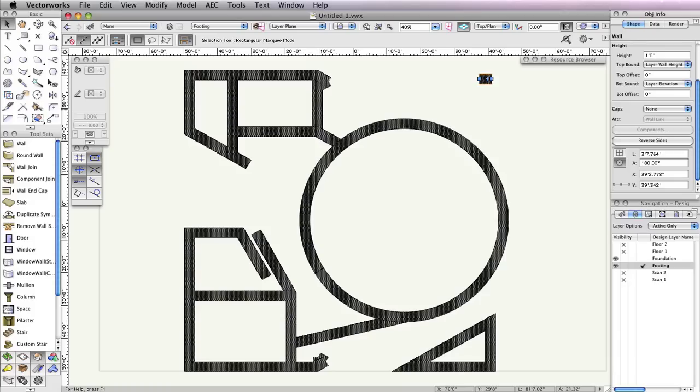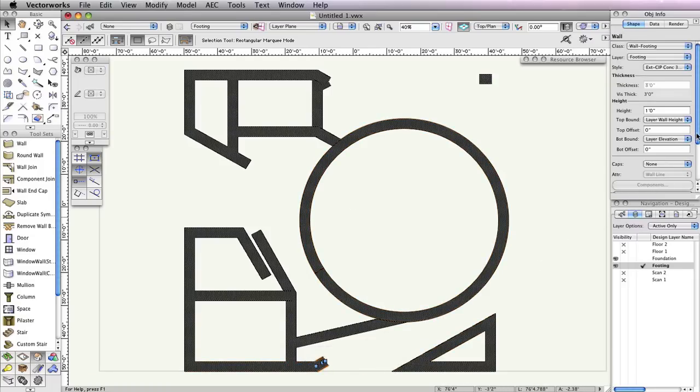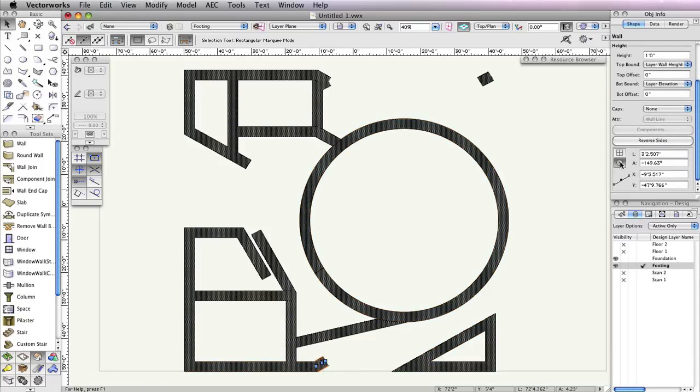Now let's fix the area with the overlapping walls toward the bottom of the building. Delete the 2 walls that are not joined to the adjacent horizontal wall. Then select the remaining wall and switch to the Polar Grid in the Object Info palette. This time, choose the leftmost position point and set the angle field to 90 degrees. The wall should now be perpendicular to the adjacent wall. You may need to rejoin this wall to the horizontal wall after performing this action with the Wall Join tool.